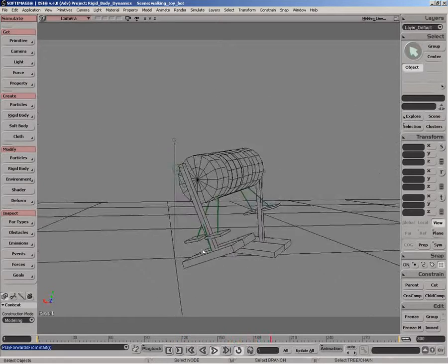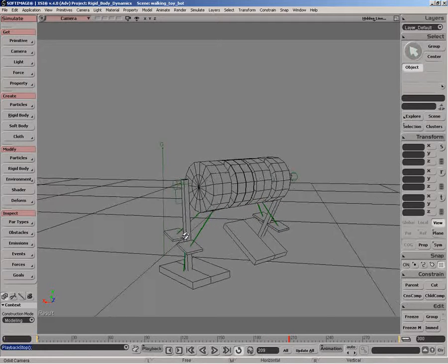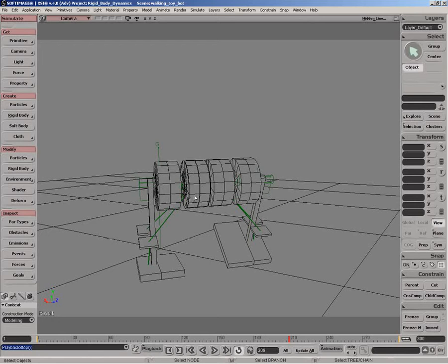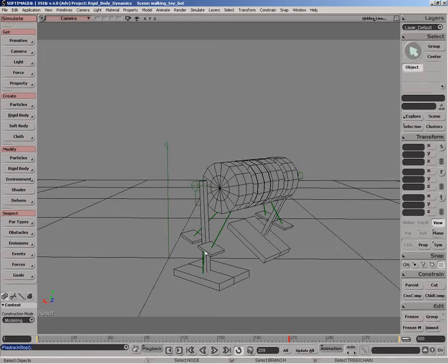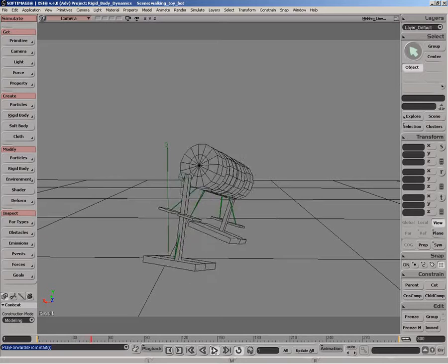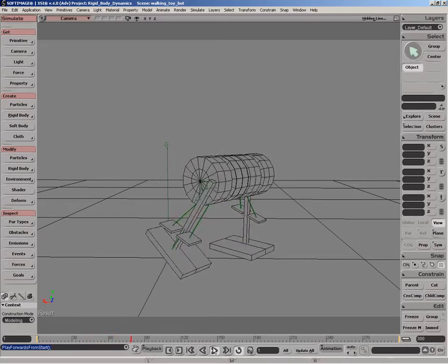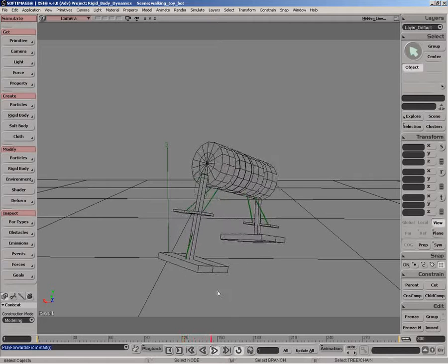And then by constraining two other active rigid body objects to the center motor, the source of the motor, we can actually focus the motion of that armature. So it's more of a vertical up and down motion rather than two horizontal. So we can actually create a balanced system that allows it to walk with a footstep.